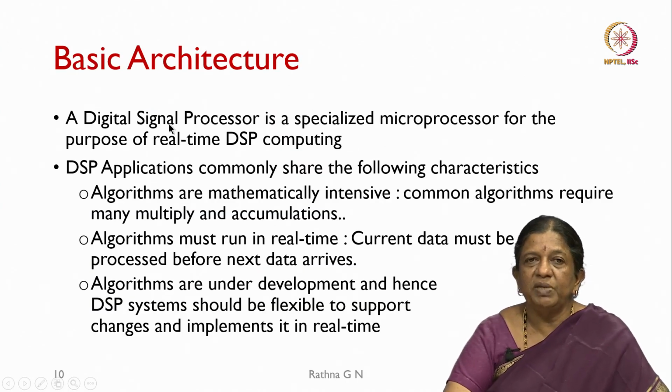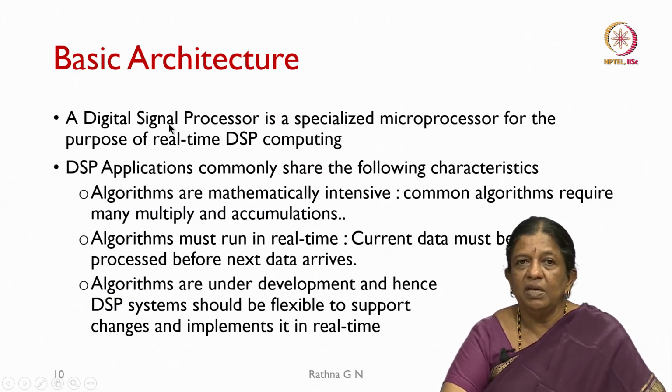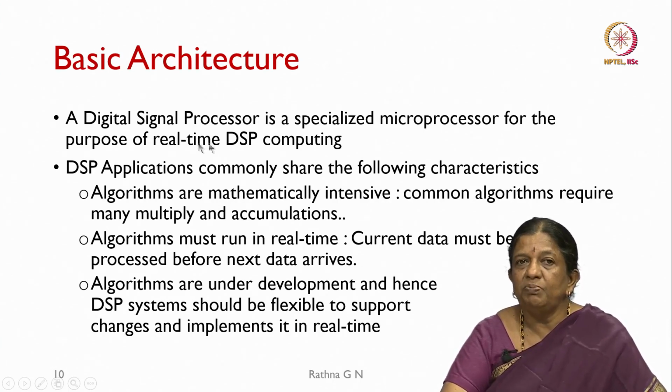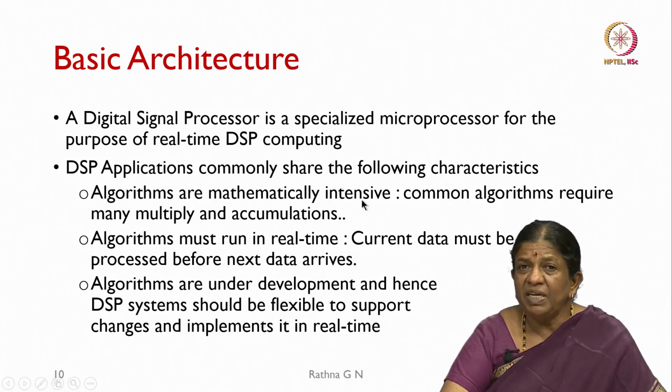So, coming to the basic architecture of the DSP, it is a specialized microprocessor for the purpose of real time DSP computing. The applications commonly used in digital signal processing are mathematically intensive, that is, common algorithms require many multiply and accumulate operations. Algorithms must run in real time, that is, current data must be processed before the next data arrives in the clock cycle.